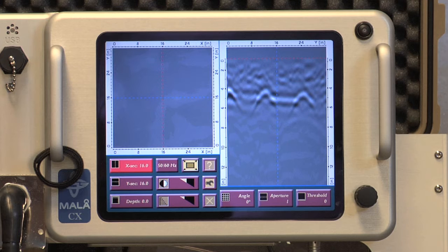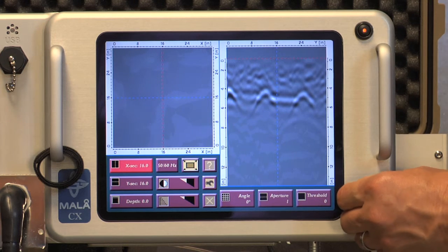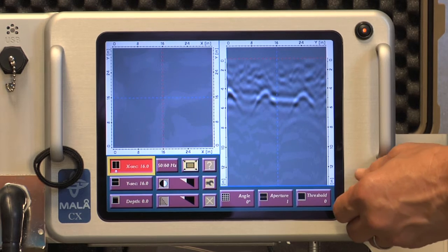The CX system's 3D imaging capability relies on the principle of migration described heretofore in the 2D function overview for depth calibration. An important step to achieve an optimized image of the concrete media is to scroll through your data selecting the X or Y icon.